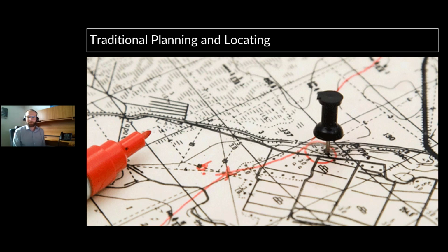So without remote sensed data, the desktop portion of the planning process was often very coarse, and it often lacked the resolution to produce a preliminary alignment that had much value. So when you took that preliminary alignment out to the field, it's not much better than starting from scratch a lot of the time. It's still a question of where should I put the road? Where should I collect survey data so I can further refine where I should put the road? So it had its issues.